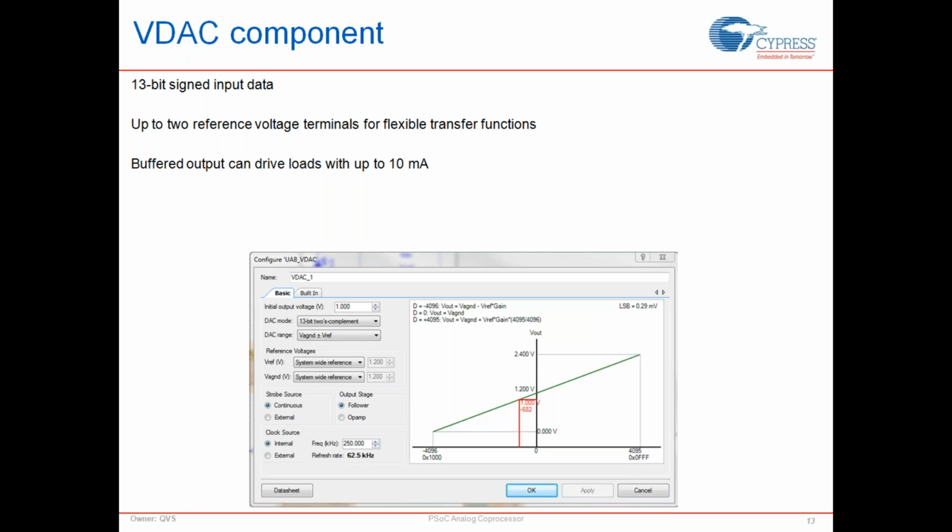The reason you want consistent update frequencies is because most times if you're trying to do waveform generation from the VDAC, your update frequency is something you want to keep constant so that you can filter it out, because that shows up as a spike in your spectrum of the output of the VDAC. So generally you would have a filter on the output of the VDAC that filters out the update frequency or the sample frequency of the VDAC.